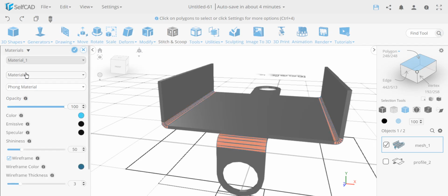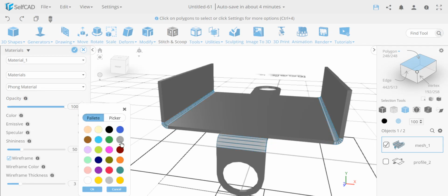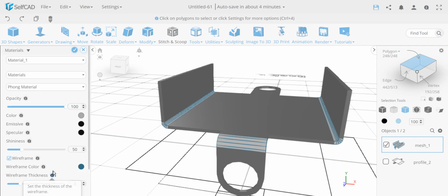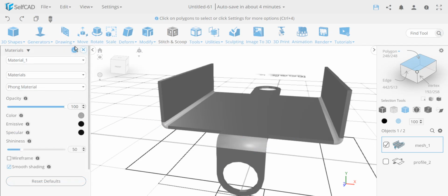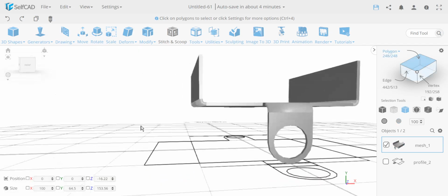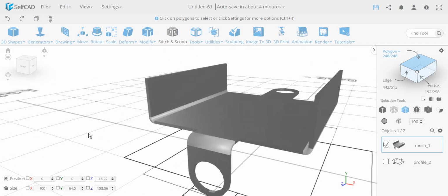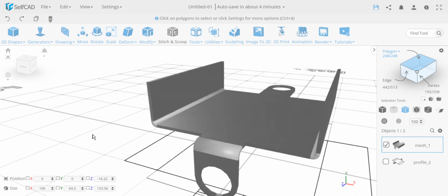And then I go to material 1, which flashes for a second, as you saw, to know what it is, but then it removes the selection color because we need to see the changes. It just flashes for a second. And then I'm going to change the color from here. Also, over here I can change the color here, and I can reduce the wireframe. Here I'm going to add actually a smooth shader as well, so it gives it kind of this nice look.